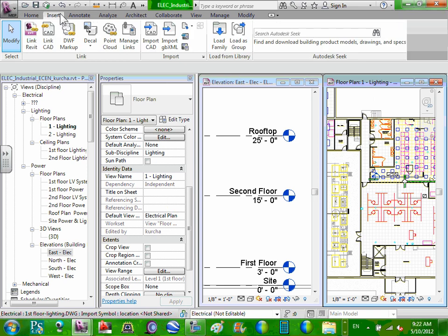Can I just walk you through it? I set them up. Well, we have a 3D model, right? That comes from the architects, and then we create a central file. When you pick up the central file, really there's a couple of buttons you have to hit, and then it will create this file for you. So I didn't set up the lighting floor here. It's already set up for me. It comes set by the system, like a floor plan cut by the system. I didn't do any input. When I did my central file, all these are set. All the levels are set by the software, so I wasn't able to change that cut plane.